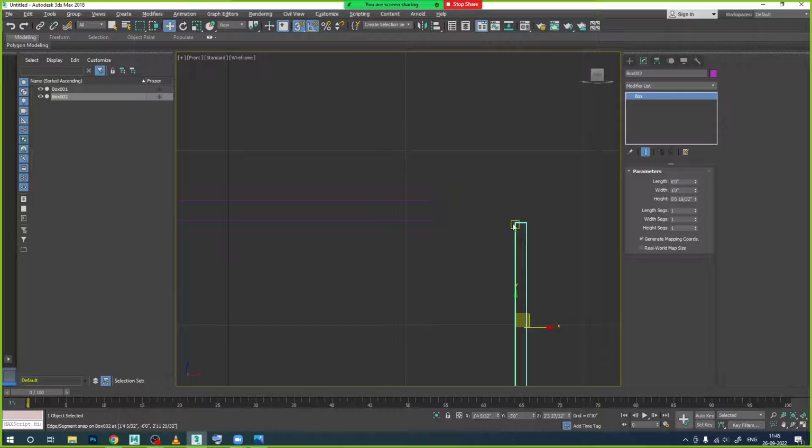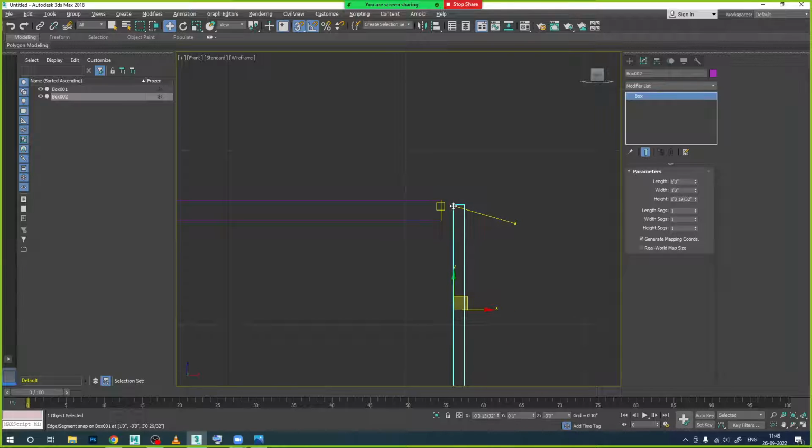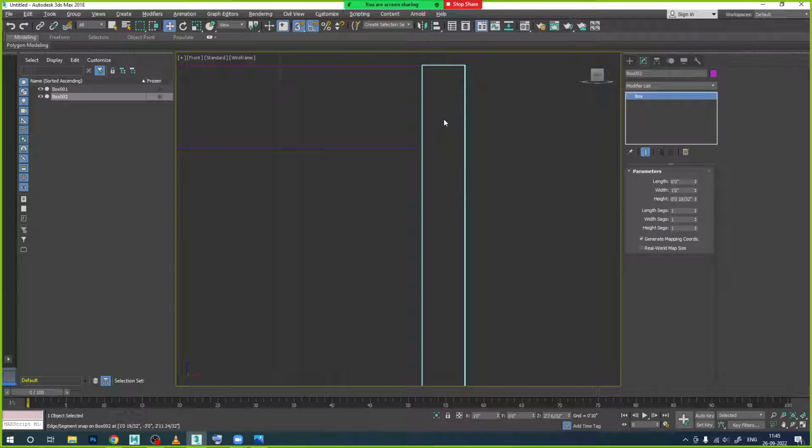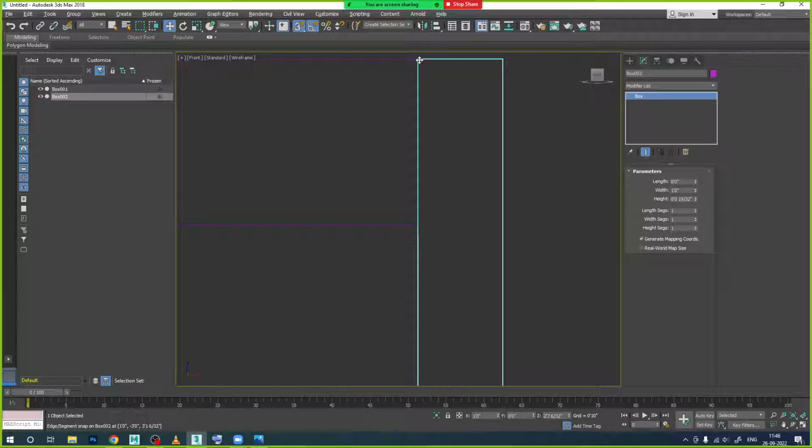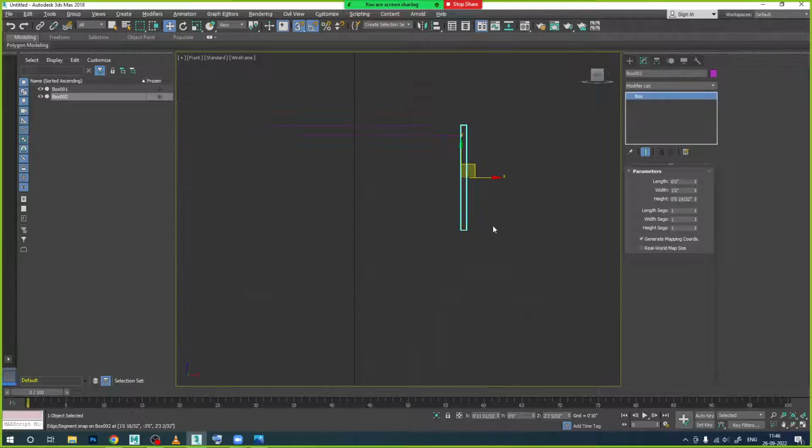It is exactly attaching to this one now. Otherwise, simply place the pointer on this corner, then drag and drop this one onto the top. See, it is attached now. Zoom and see whether it is attached perfectly or not. Now you see the blue or green color box indication? You are properly attached to the corner on this one. Release it. Clear?